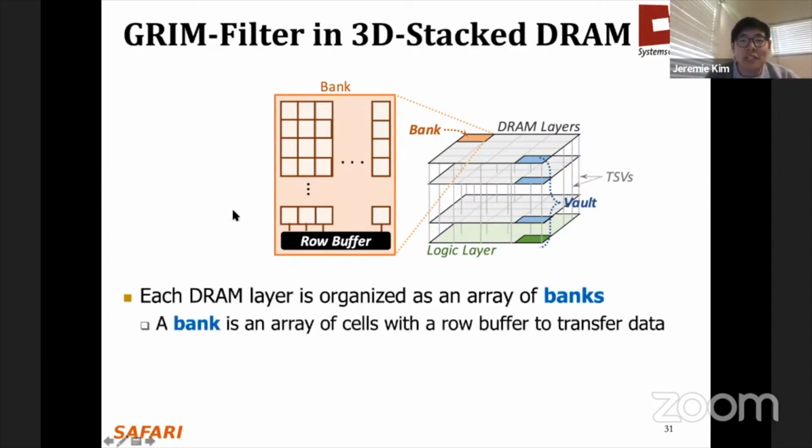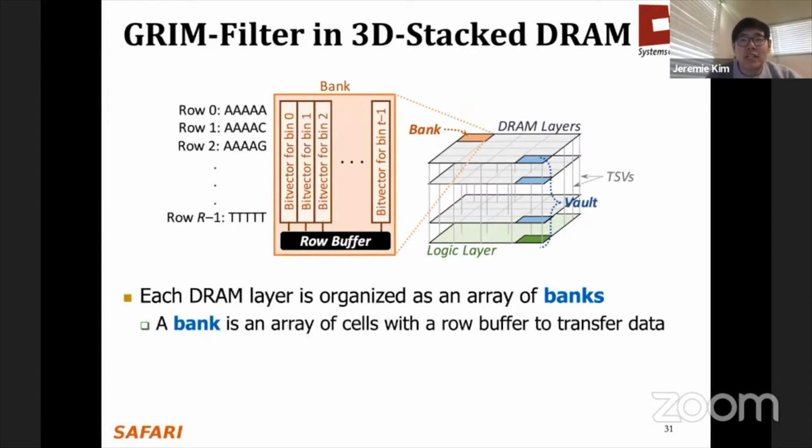We now show the distribution of bit vectors across the DRAM arrays to enable parallel processing of the bins. Each row represents a token's occurrence across many sequential bins, and the row of the appropriate tokens gets queried to find a vector showing the occurrence of the token across many bins. And these are the vectors that are brought down into the logic layer to be operated on.